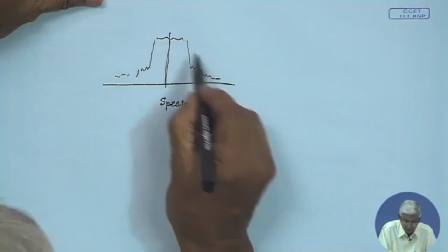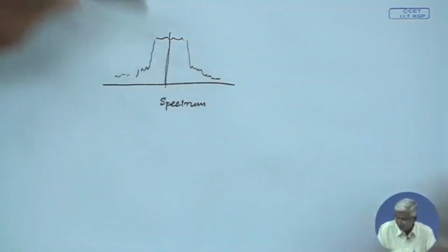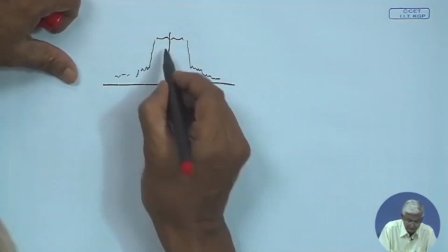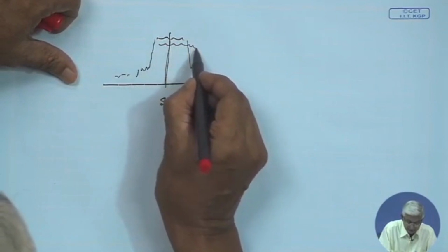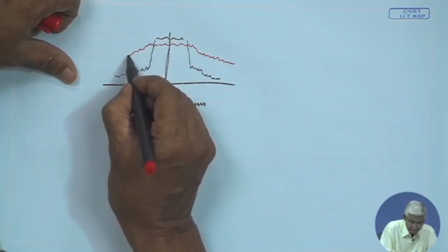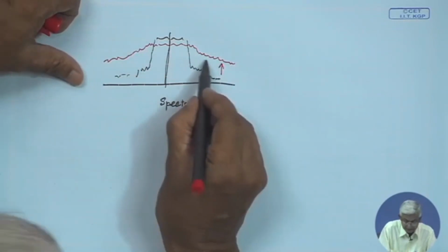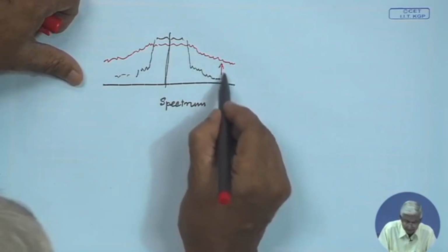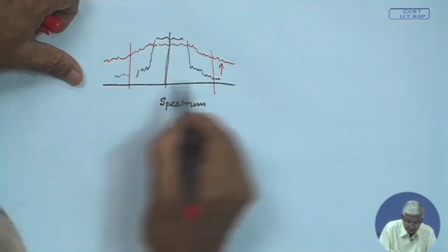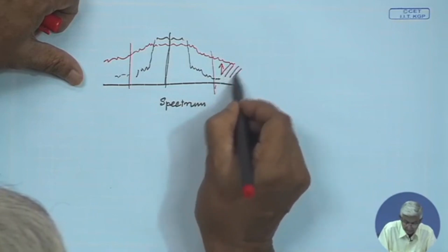Now, due to intermodulation, the spurious gets generated, and the spurious will be spread at different frequencies. So, the new spectrum will be enhanced, and it spreads further, the amplitude spreads further. So, if your operation area is this and the adjacent channel is coming, you are interfering.